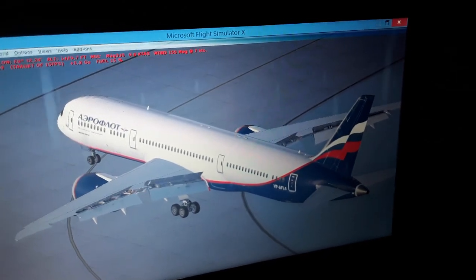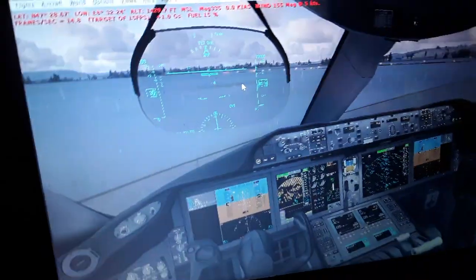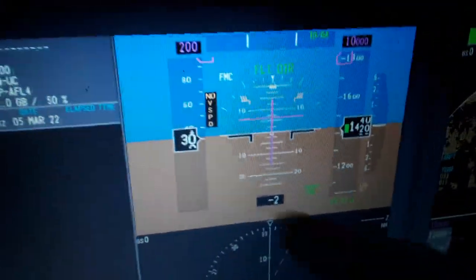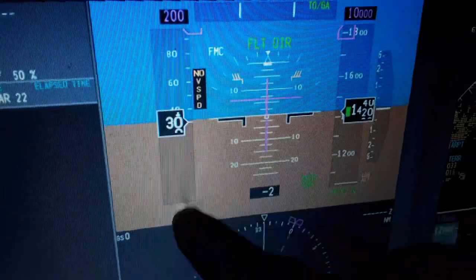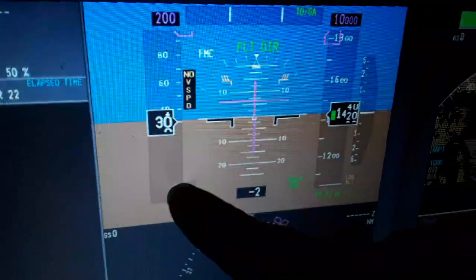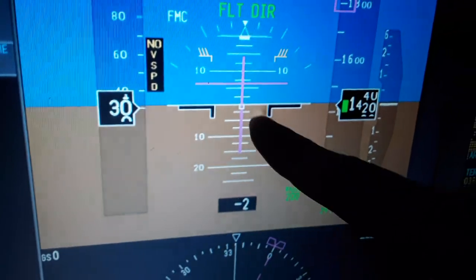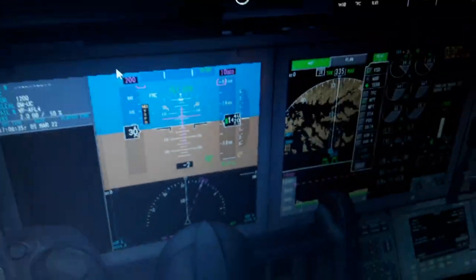So we need to apply over here the stall avoidance maneuver in the air. We need to monitor for the stall speed here all the time. When we fly, we have the primary flight display, the airspeed indicator that I show you. You're gonna see the stall speed display with a number and red indication. We need to avoid reaching the speed of the stall for the angle of attack over here of the stall of the wing.